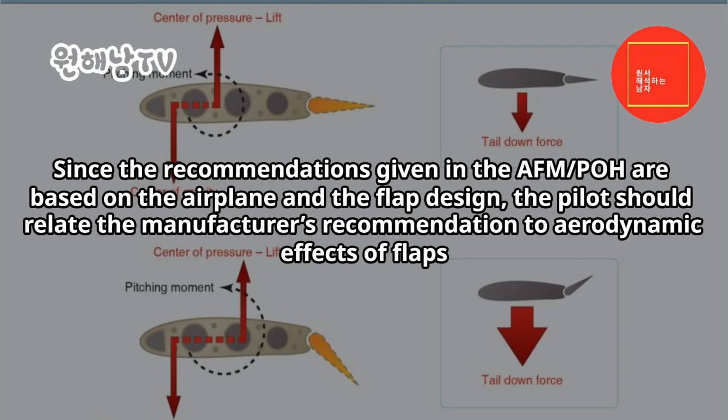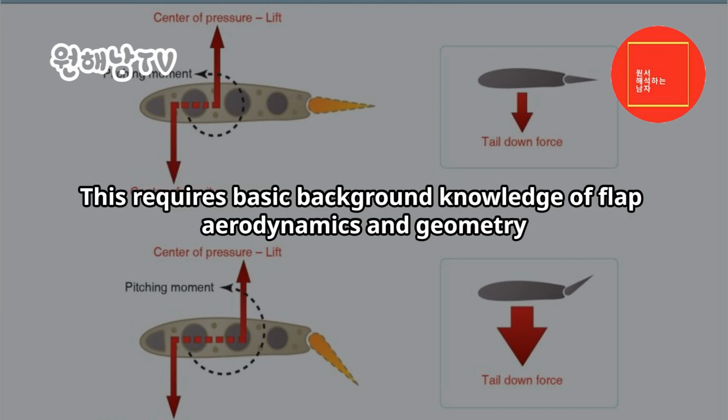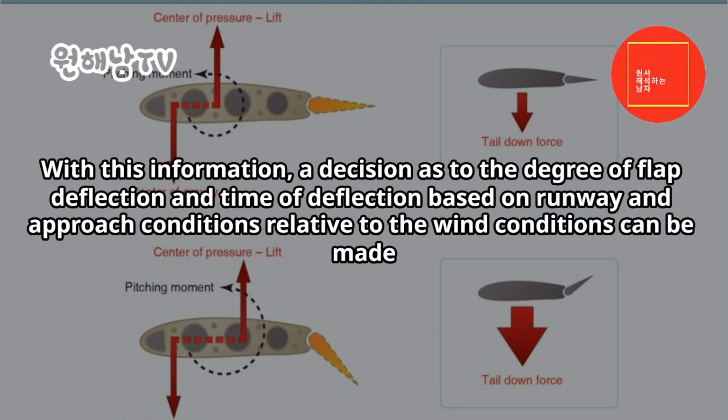Since the recommendations given in the AFM/POH are based on the airplane and the flap design, the pilot should relate the manufacturer's recommendation to aerodynamic effects of flaps. This requires basic background knowledge of flap aerodynamics and geometry. With this information, a decision as to the degree of flap deflection and time of deflection, based on runway and approach conditions relative to the wind conditions, can be made.